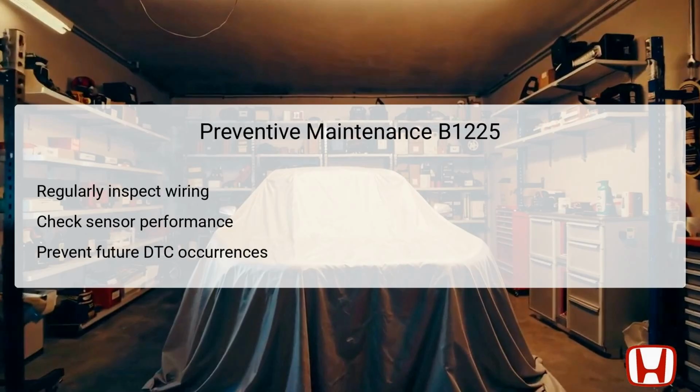Preventive maintenance is vital to ensure the longevity of the in-car temperature sensor and its associated circuitry in the Honda Odyssey. Regular inspections of wiring should be part of routine vehicle maintenance, helping to identify potential issues before they escalate into larger problems. Corrosion, wear, or loose connectors can be spot-checked when performing other routine upkeep tasks, such as checking fluids or replacing filters.